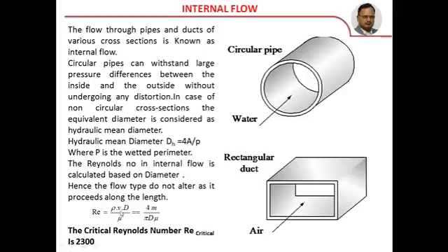And further we know that the mass flow rate of fluid through a pipe is equal to rho into area into velocity. So therefore, when you multiply both numerator and denominator with A, the rho A V becomes m, and in the denominator A is pi by 4 D square. So that 4 comes to the numerator, D square and D cancels, you will get pi D.